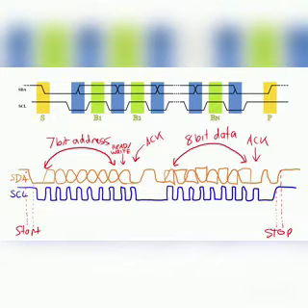After the block is complete, there are 2 different things that can happen. If the slave device is okay with the data that was sent, then it will acknowledge the transaction and it will pull the line low. If it's not okay, it will allow the line to float high, which indicates that there's a problem with the transaction. The first block of data that is transmitted is the address of the slave.